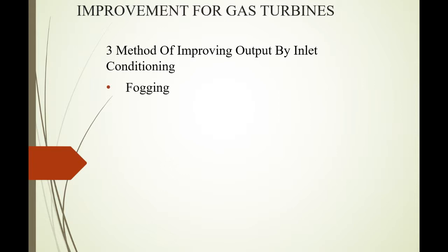Fogging involves injecting atomized water into the inlet air stream downstream of the inlet filters. The system carefully controls the amount of water injected to ensure no large droplets of water are ingested into the compressor.